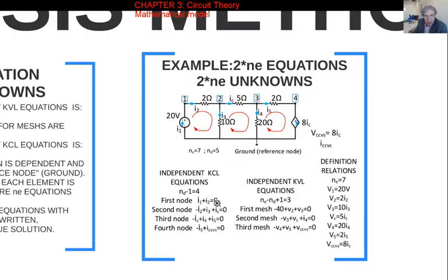Just in parentheses to inform you that this reference here, the blue reference for the independent voltage source, must be chosen like that. For the other ones there is no rule. You could choose the other blue ones randomly, except this dependent source as well. So these 5 current references could be chosen as you like.